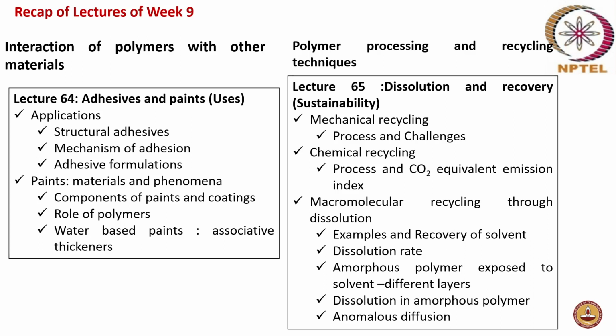Further going down into the polymer structure, the next layer will have much lesser solvent, but it would have plasticized the polymer. So it would have become more rubber-like in this layer, with a large amount of segmental mobility. And the final layer might be a very glassy layer, where the solvent has not yet diffused.